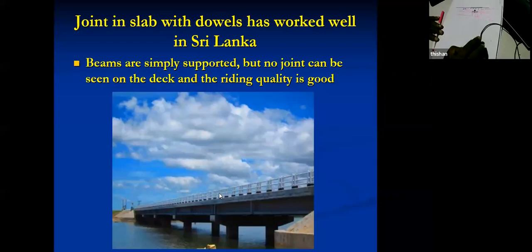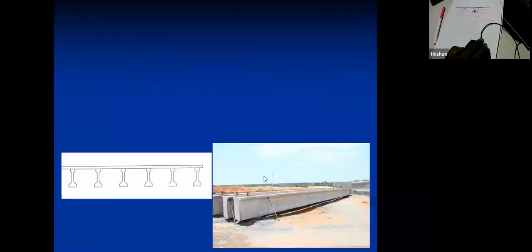that there's a connection, but it's flexible. There's a connection between two adjacent beams on each span, and there's a connection with the dowel, but not a complete connection. Any minor movement can be easily accommodated. So this is the kind of joint that we adopted at this particular bridge, as well as Orugodawatta flyover. And so you can see you can use I-beams,